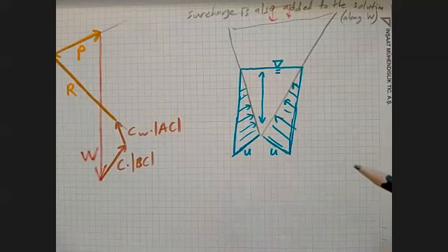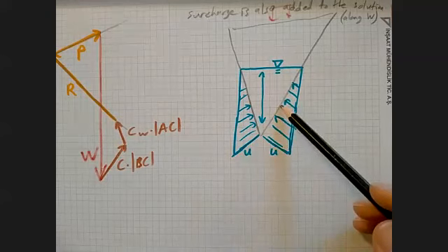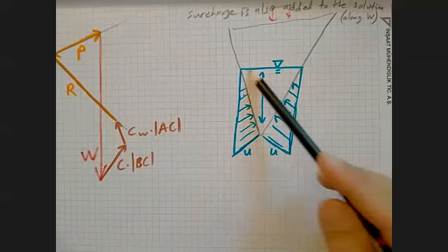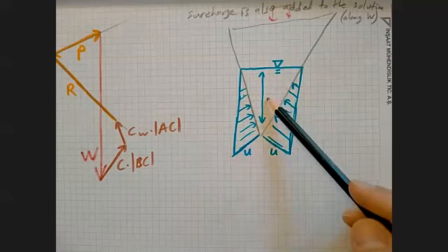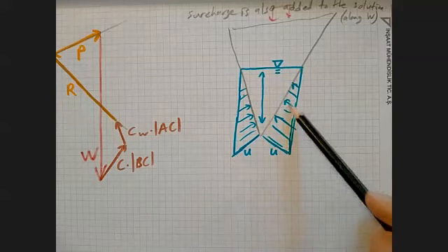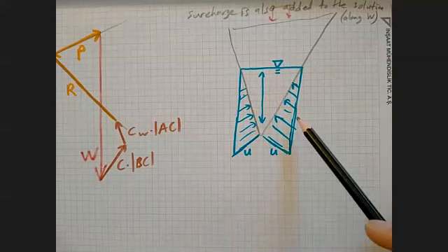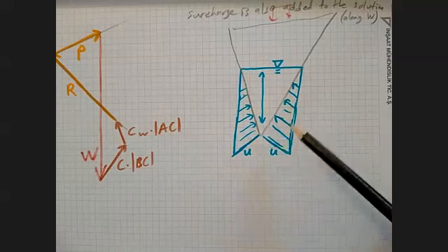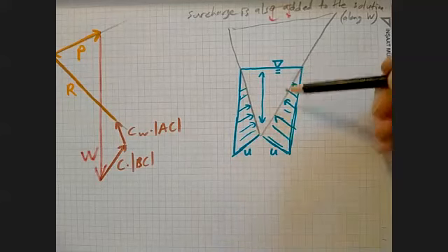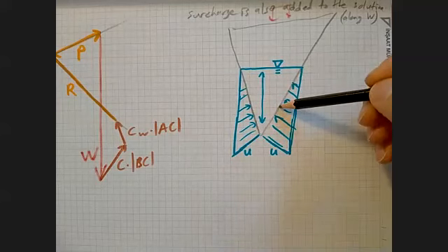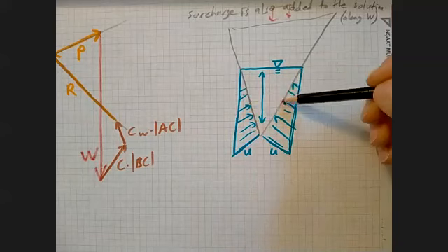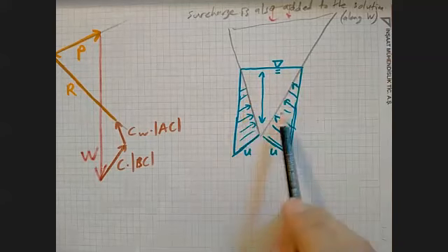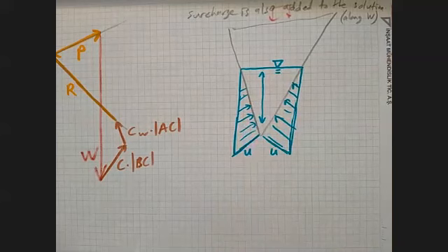So the forces that the sides of the cup are acting on the water, which are equal to the pressures the water acts on the sides of the cup due to the action-reaction principle. So the forces that are on the sides of the cup, their horizontal components and vertical components are in equilibrium separately.